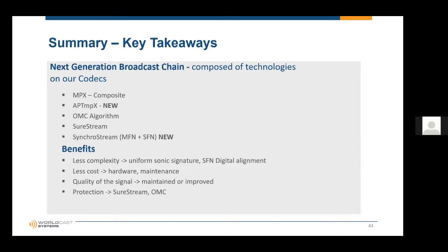On your MPX, the composite version. If I were to move my audio processor from my transmitter site to my studio, how accurate is the audio going to be going into my transmitter as compared to the input, as far as any sort of overshoots, artifacts, level differences, etc.? Are you doing MPX over AES, or are you doing analog MPX with the coax? It would be analog MPX, and then running HD with a synchronizing device to keep them linked.